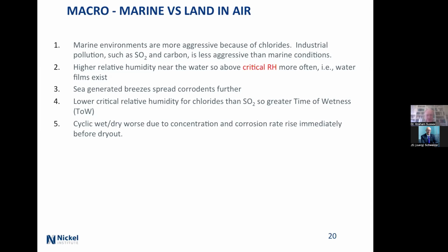And so you'll have greater times when there's actually moisture on the surface. And that's used as a characterization of surfaces, the time of wetness, TOW. And if you've got cyclic wet and dry circumstances of concentration, then the corrosion rate goes up. That's why a cyclic salt spray test is much more aggressive than a simple constant conditions salt spray test.